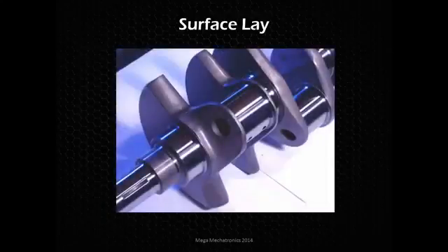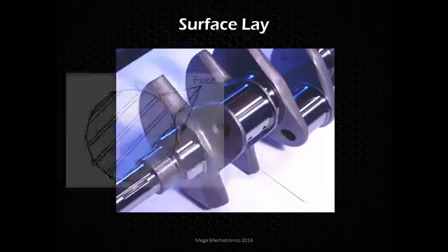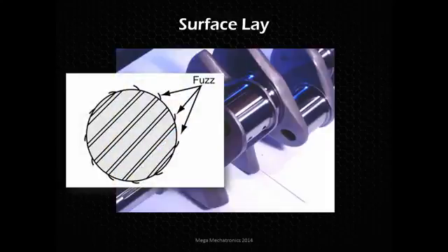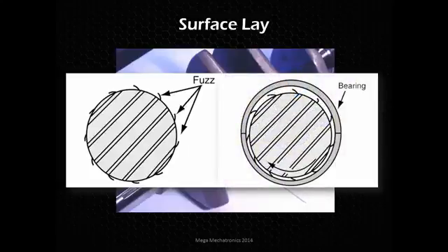And looking at a crankshaft here, you can see the journals are highly polished, and that's actually very important. That surface and how you finish that surface, because there is this attribute called fuzz when you polish these crankshaft bearings, and depending on the direction of polish, you're going to fold that material over and create this sort of fuzz, what they call it. The picture is a cross section of that shiny journal, and that direction is very important.